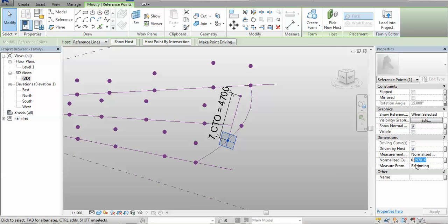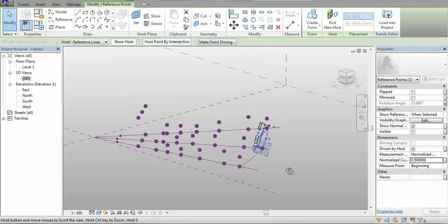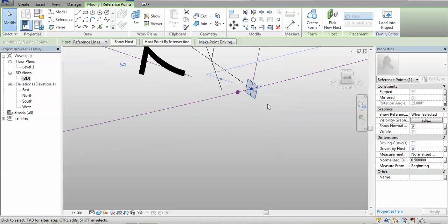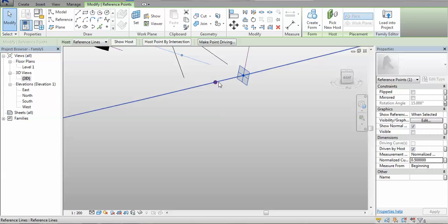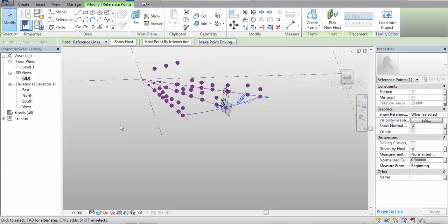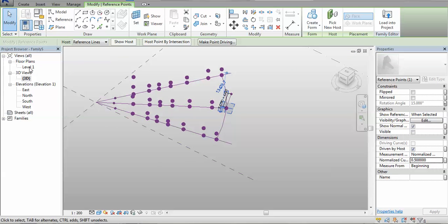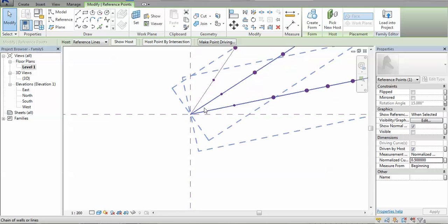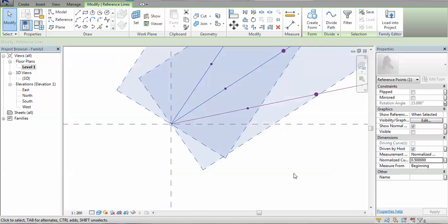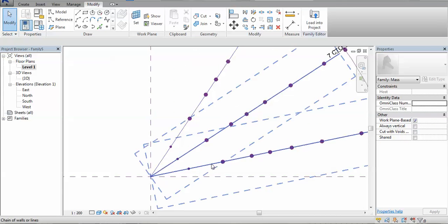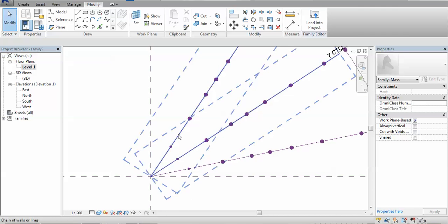So I clicked on the point down below. Let's change the value to 0.5, so 50%. Now, if I zoom in here, you can see that it looks fairly good, but it's not being placed at the exact same position as this point. And the reason for that is because these lines that I originally created here have a different angle between them. So the segment of the angle here and the segment of the angle here is different.